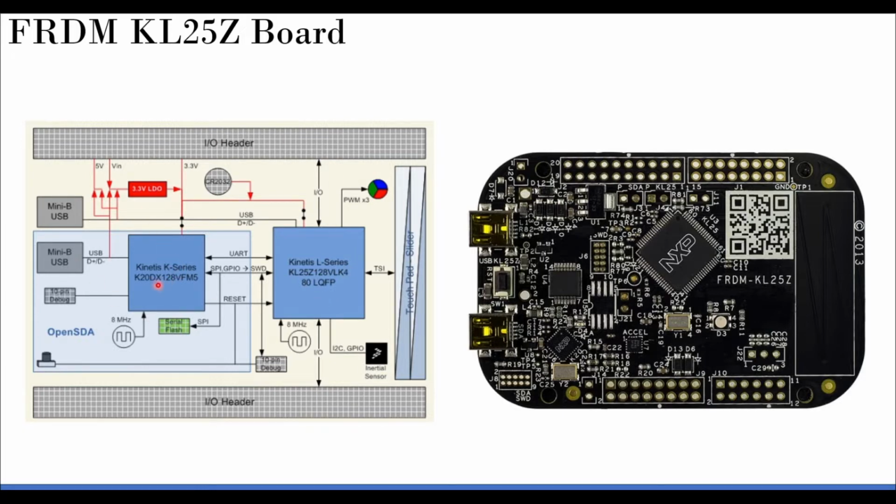And on the peripheral side, there is a debugging option which is shown here. Serial debug access, what we mean by OpenSDA. There is a definite interesting aspect: there is another microcontroller which controls the serial debugging access. That's the major part. And then of course there is a coin cell. You can use the coin cell to operate this board. You don't need to power it from the external side. If you want to power it externally, you will use the USB power. There is no explicit power supply or power jack for this board, but it is through USB powering.